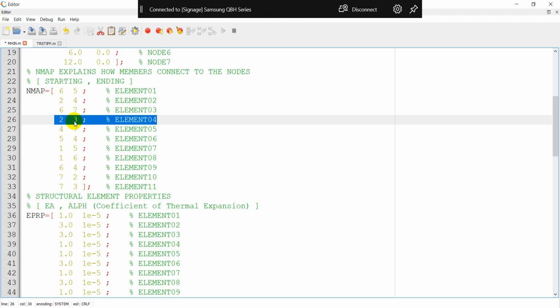So this one is quite simple. It's not tricky at all. When you plug in the element stiffness matrix to your system, you just bring the 3, 4, 5, 6. You just bring this matrix and add it into the entries for rows 3, 4, 5, 6. So it is just connecting, right?